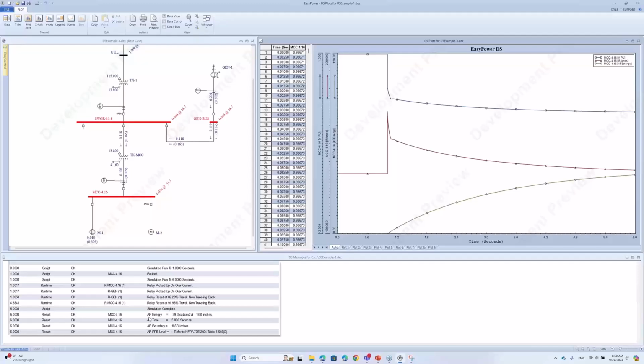So you have a much larger arc flash energy. You have much less fault current. Remember, the fault current goes up after the fault is applied, right? Just now for the static excitation system, because of the large fault current, the relay can operate properly. In this case, the relay will never clear.